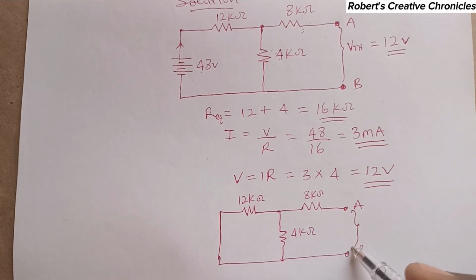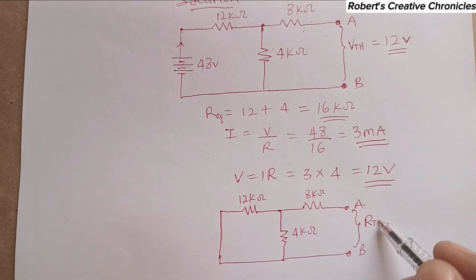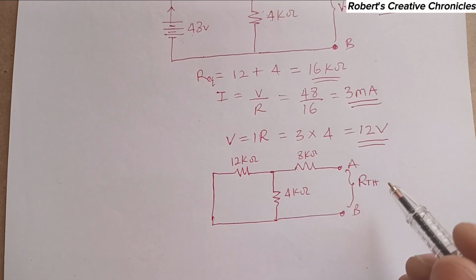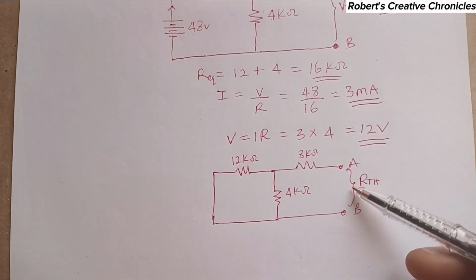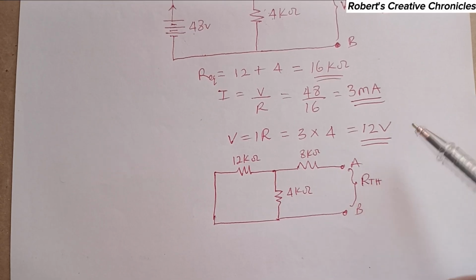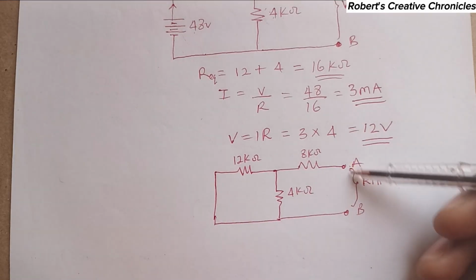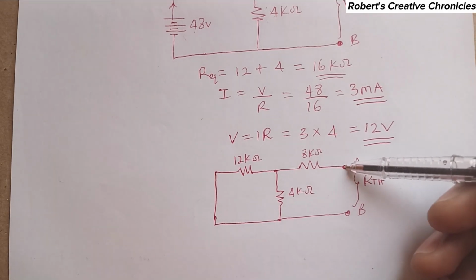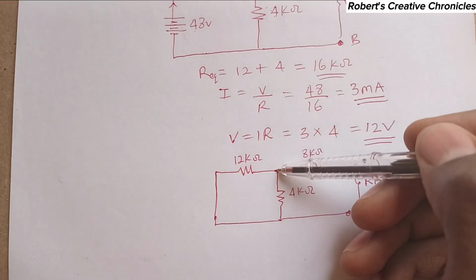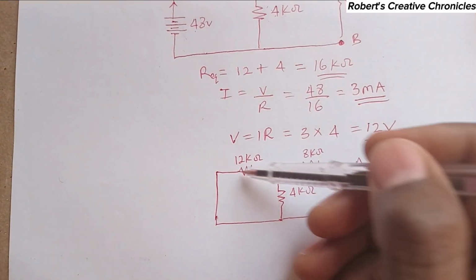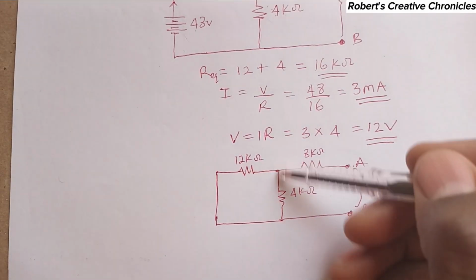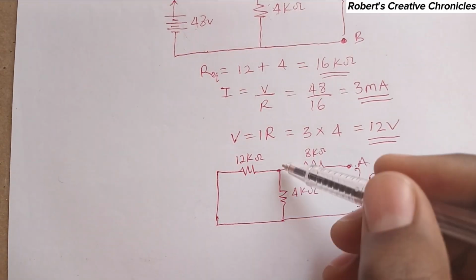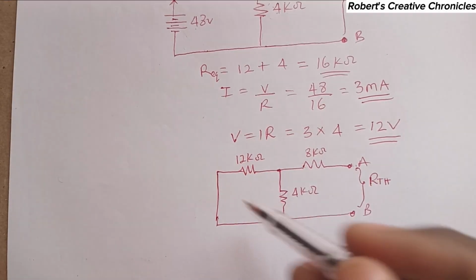So now we are going to find the Thevenin resistance, which is the same thing as the open circuit resistance. So we'll look at this terminal. This resistance will be calculated when looking from here. When a current source is connected and the current passes through terminal A, the current will enter here, and when it comes to this node, it will divide into 2. So this and this are parallel, since different portions of the current enter them.